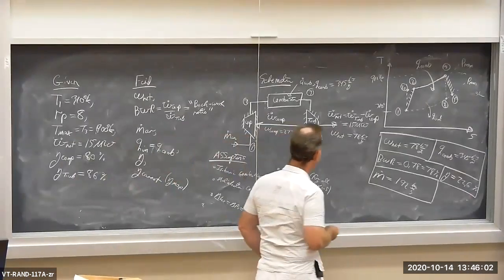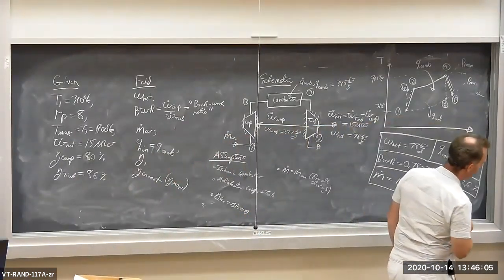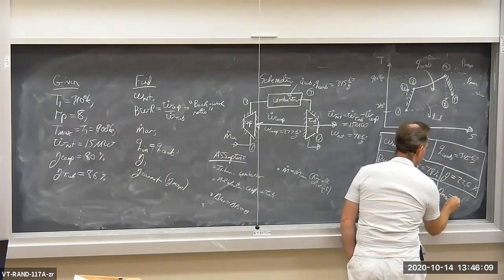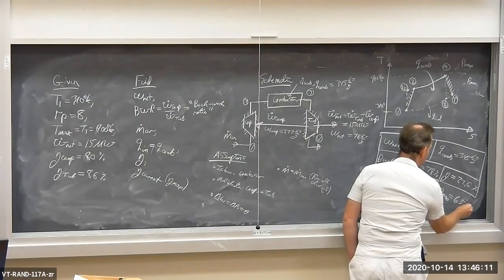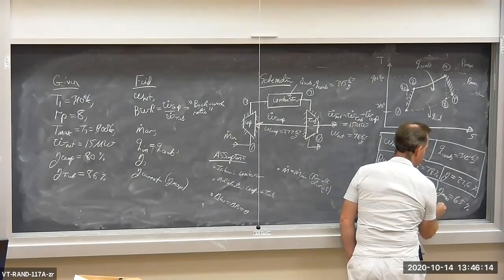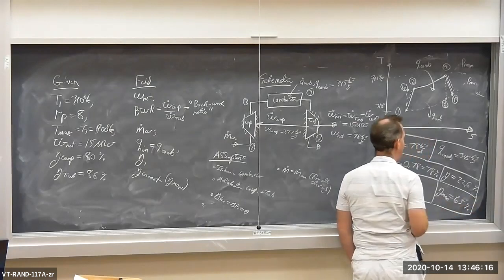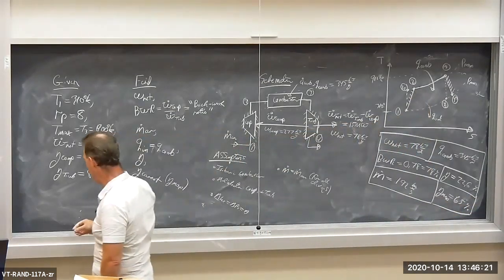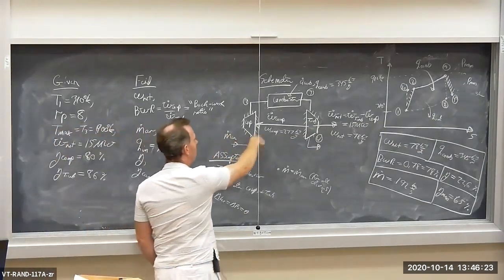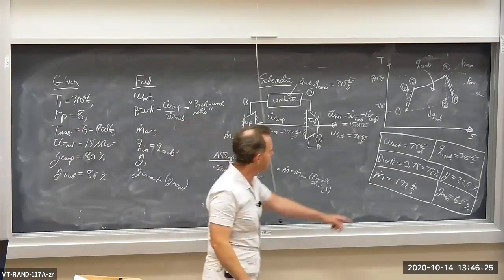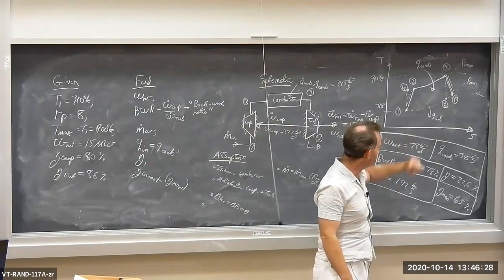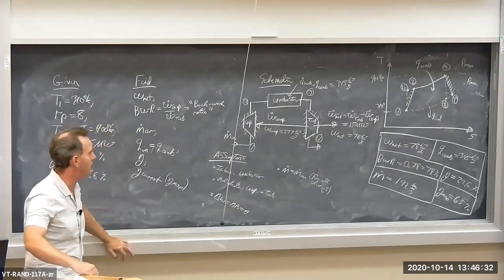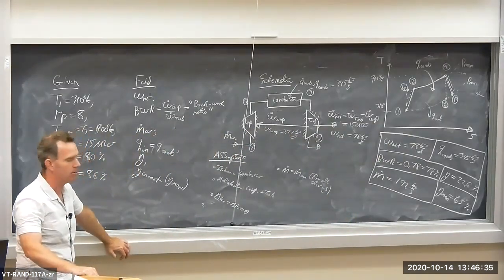So this device only has a 22% thermal efficiency, whereas the Carnot, or the maximum efficiency, is 65%. It's due to the fact that the heat is being received at low temperature for much of the cycle, and we have all these inefficiencies in the turbine and compressor. It also has to do with the heat being rejected at temperatures other than the minimum temperature, which results in heat transfer across a finite temperature difference outside the device.